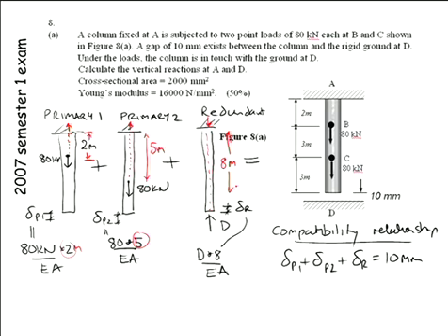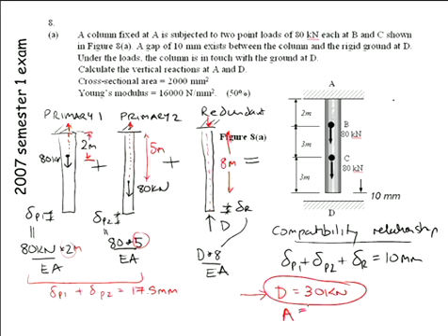So when you plug in these two deflections here, primary 1 plus primary 2 actually add up to 17.5 millimetres. So that's telling us we do have contact. I'll leave you to finish that one off. You'll get a D force equal to 30 kilonewtons. And thus straight away you know your A force, because from equilibrium here, you would say A plus D minus 160 equals 0. So therefore you know A equals 130 kilonewton.